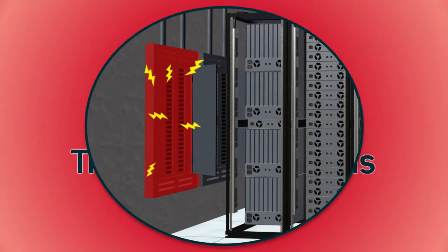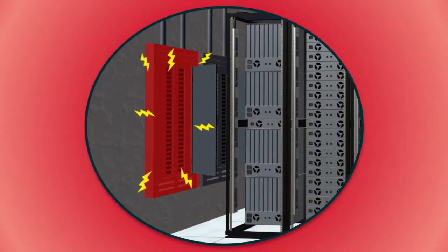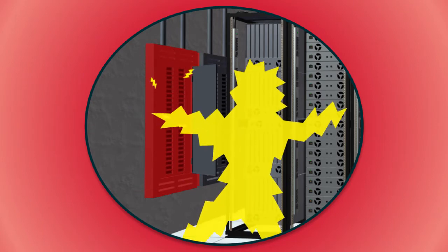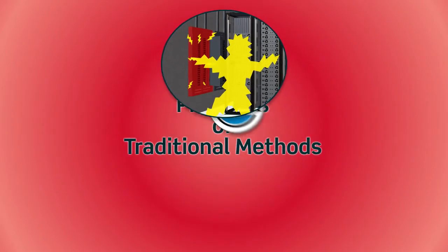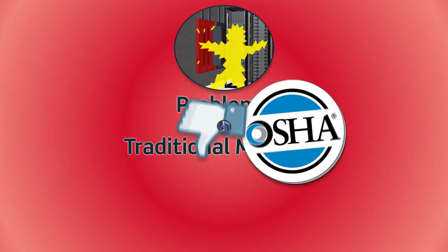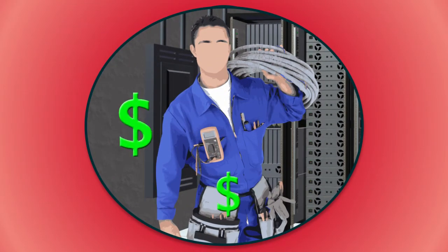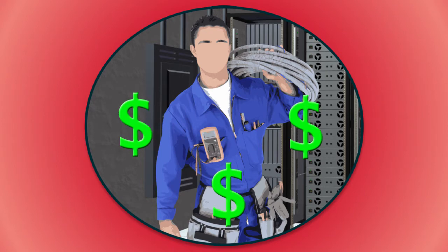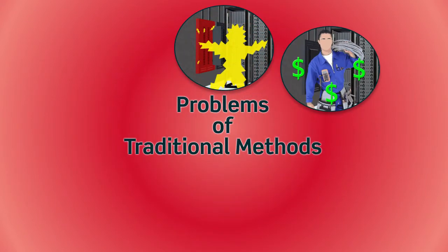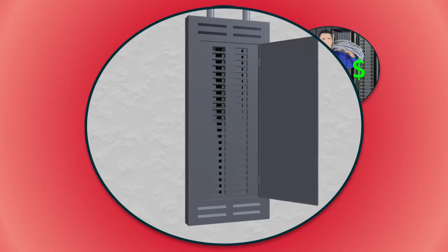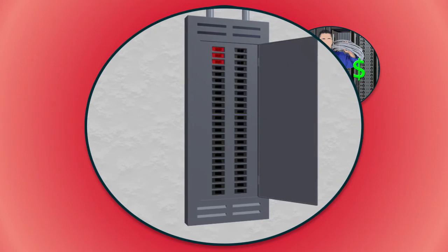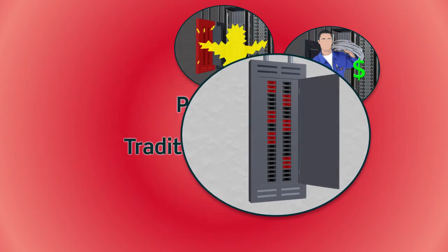Changes have to be made hot at the panel or busway. Changes made while the system is hot create risk to the electrician and potential non-compliance with OSHA regulations. An electrician or contractor is required to reconfigure power on the data center floor. There are larger than necessary domains of failure due to the limits of the National Electrical Code. The domain of failure is the number of receptacles affected by an event that trips one or more circuit breakers.